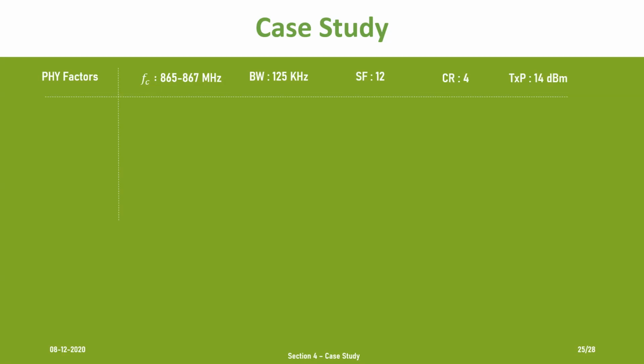Now, you know all these things that I've just written down. If I have even a slight change of 1 or 2 digits in any of these, it essentially changes the entire picture. If I'm not using 14 dBm but 20 dBm for transmission, my range might get 1.5 times or 2 times. So you must ask these questions when you see somebody claiming what range they have gotten. I'm just listing down the other things that matter that we have understood. Now we have a greater understanding of all these factors. The other factor within which this case study was done was the enclosure. The enclosure was a car. We were roaming around a city, lying inside a car on the seat, and hence the transmitter height was 0.5 meters. The receiver height, as with all our network deployments, is massively high.